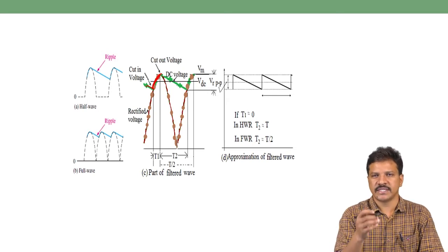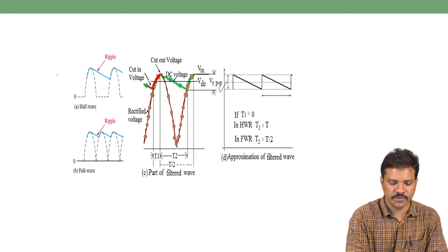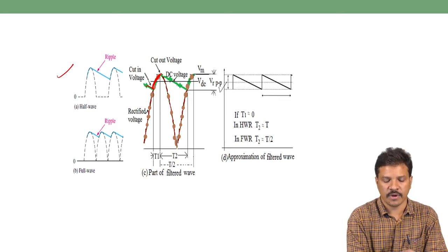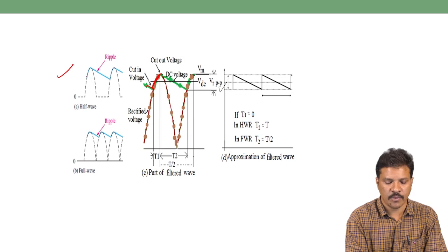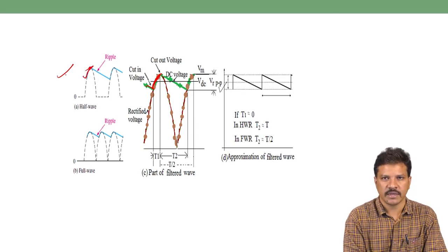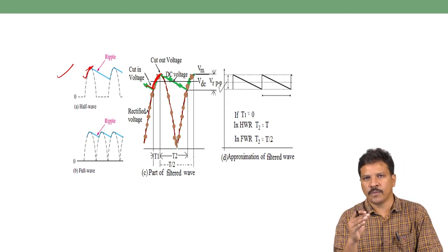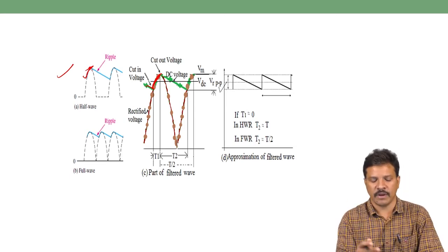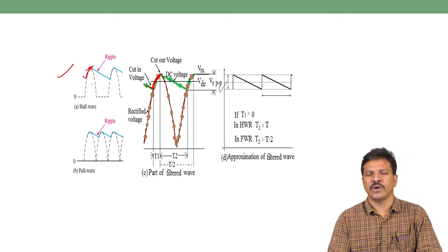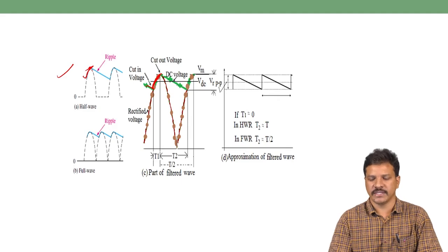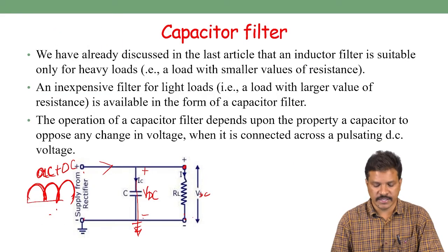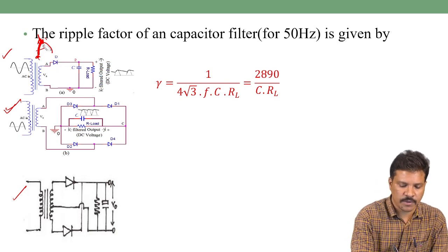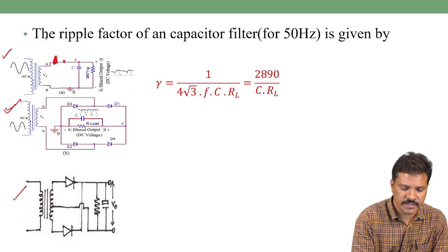What happens when the input voltage falls? Assuming our case is a half wave rectifier, the dotted line represents the half wave rectified output passing through the capacitor. Up to this point, the capacitor charges to the maximum voltage. When the rectified output waveform then falls below that maximum voltage, the diode gets reverse biased. When the diode is reverse biased, it is an open circuit.